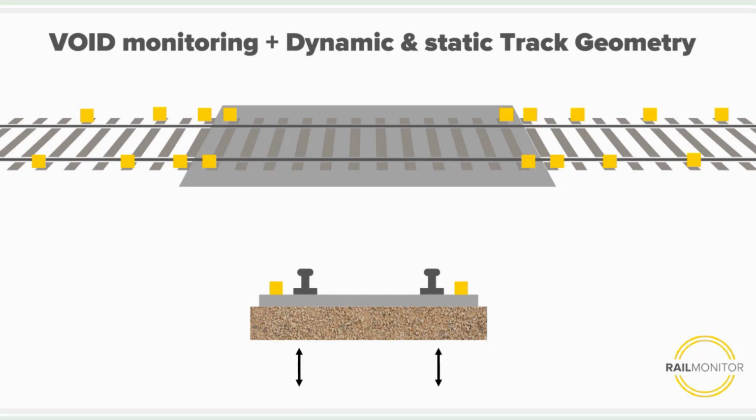But having a monitoring system, monitoring the dynamic track geometry, they are then able to run up to 160 kilometers per hour. So this will also mean, of course, that they do not need to change the timetable. They can keep up the customer satisfaction. So this is not just to monitor instability, it's also to actually put value to the passengers, even though they have some construction sites and some construction work.